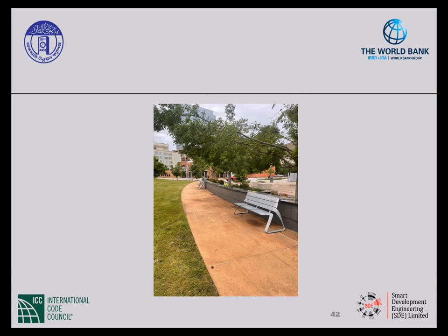So here's an example of an accessible route. Let's see if it complies. Benches are provided every 300 meters. The width of the paving is at least 1,200 millimeters wide and has not been reduced below 900 millimeters at the bench. But what about the overhead clearance? It appears that the tree branches are less than 2 meters above the path, so this would not comply.